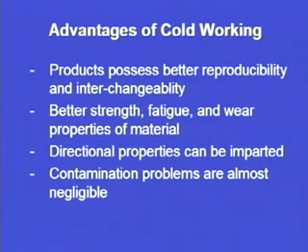Fatigue characteristics basically come into picture if we have some surface cracks. If there are small cracks of micro size present on the surface of the final product, whenever it is used under cyclic loading or any kind of load where the load is varying with time, the chances of the propagation of that crack are possible.